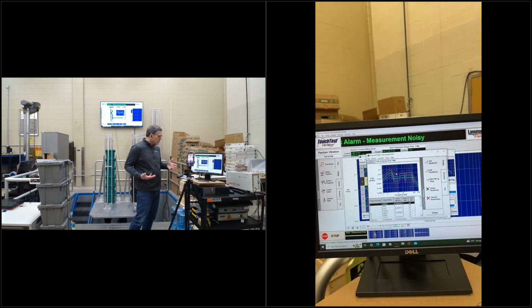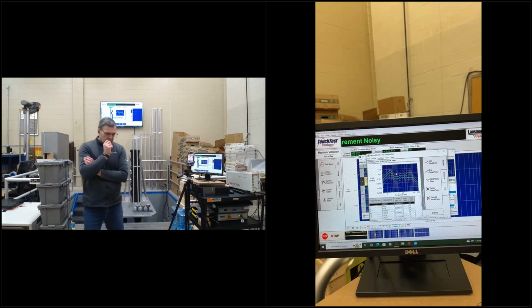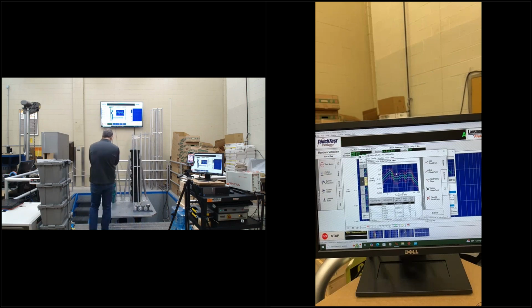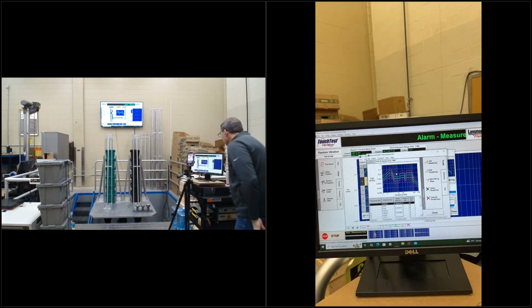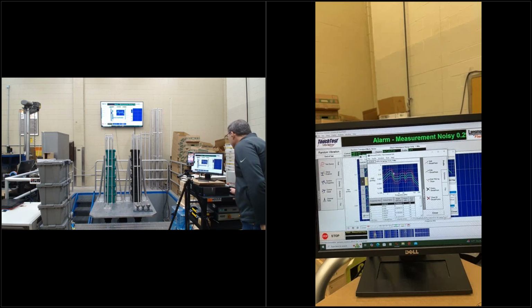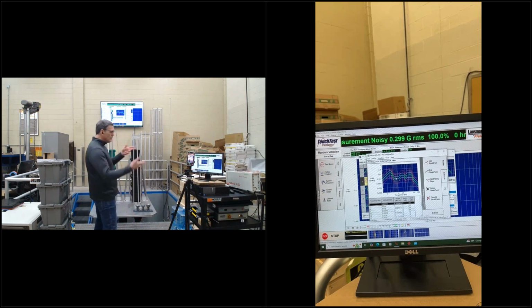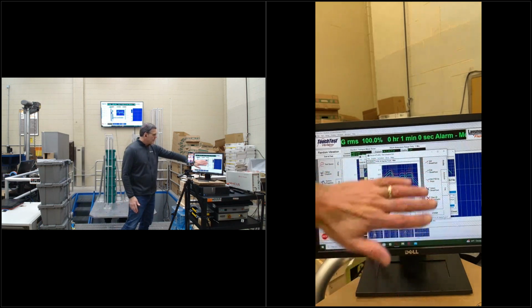You would not want it to bounce in the 3 to 4 hertz range, nor would you want it to bounce in the 16 to 20 hertz range. You'd want the resonant frequency characteristic of the load to be in this valley, not the plateaus or the peaks. That's one of the ways you would use the characteristic fingerprint of the real world transport environment to say, I can't change that. I'm going to have to deal with that.